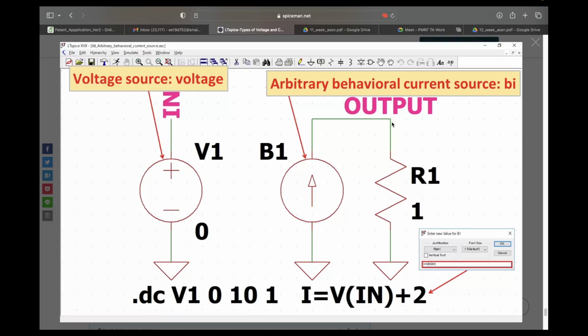In that, you will have the magnitudes of first harmonic, second harmonic, and third harmonic. You just need to verify the magnitudes with whatever you have calculated analytically using current injection. Okay, okay.